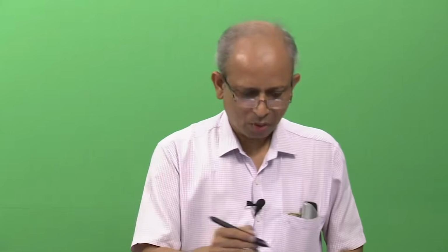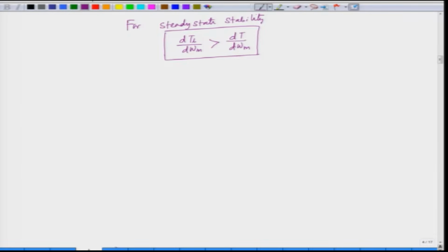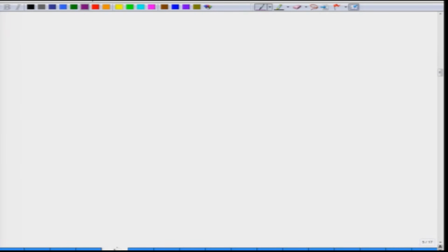Now, let us go further and we will discuss what is called load equalization. Now, what do we mean by load equalization? We have various types of load, as we have already seen: we can have a fan type of load, we can have a traction load, we can have a constant power load. Now, we have some special loads which are pulsating in nature. The load torque does not remain constant, it changes with time and it goes up and down.